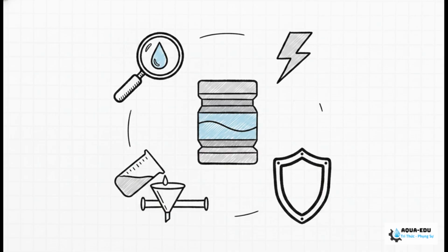When scale does form, it acts as an electrical insulator, effectively killing your water splitting process and destroying your resistivity. Routine monitoring of your RO permeate is genuinely the only way to prevent a failure. If it does scale over, CIP acid washes can recover the module, provided you catch it in time. And adding those mixed bed guards offers absolutely critical secondary protection for your entire plant.